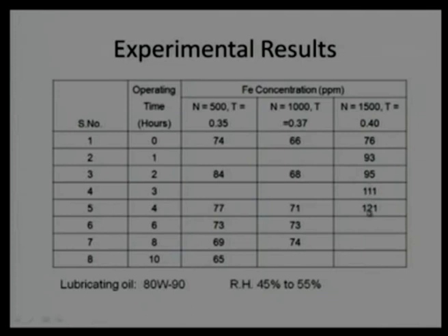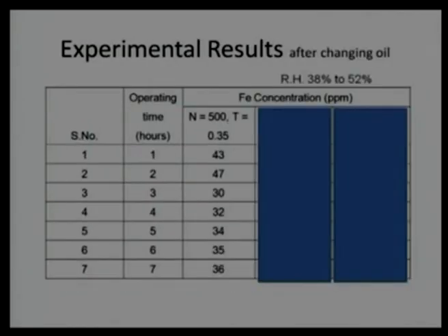That is why we are getting wear particles, and the particle percentage is increasing with increasing speed. If it were the mixed lubrication case, the percentage would not increase, it would come down. So, that is why we feel that these experiments are showing results related to the boundary lubrication mechanism. Let us see other results.